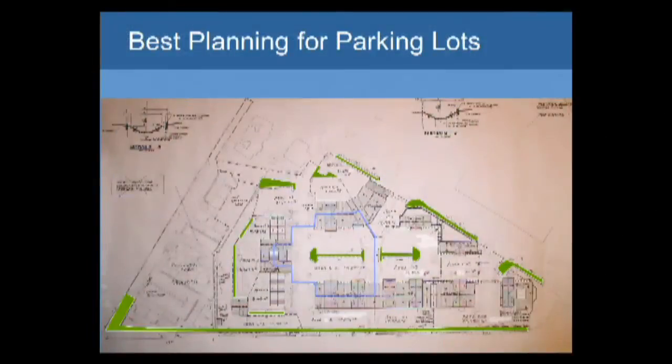So for parking lots, again, this is using the median strips. Now I will point out here that I was very happy on the day a little more than a decade ago, the first time I laid out a drainage management area and figured out how I could locate a bioretention facility, because it was this one right here, and the 4% using the dog bones on the end worked out perfectly. And it's worked everywhere in the state, and from that point, I made it my mission to get written into permits that 4% could be used, and I was successful everywhere in California except the Central Coast, where we have to go to 7% typically. As a rule of thumb, as you're doing your iterations with the calculator, that's a good point to start.